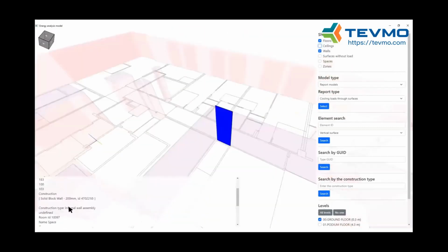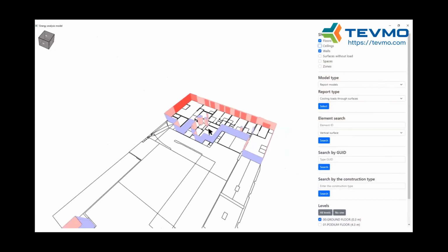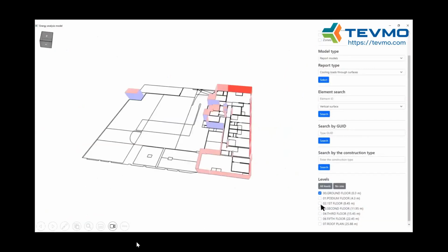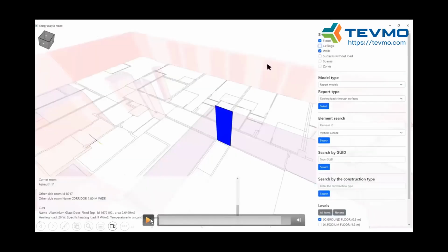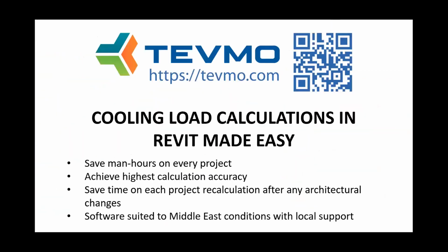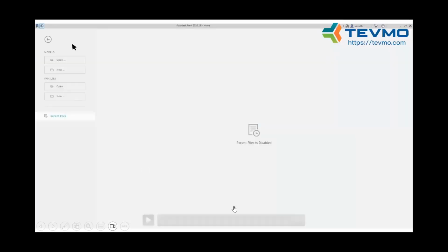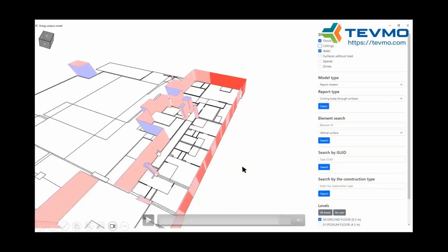And you see that all the shafts are there, all the walls, and you can check all the values of cooling loads for them. And what's important is that this floor was the ground floor. And you see that here the walls are a different color. That means that this parking is unconditioned. So you don't see the parking, but you understand that it's not a street there, but some unconditioned space. And when you press the wall, you see that this unconditioned space is 35 degrees.